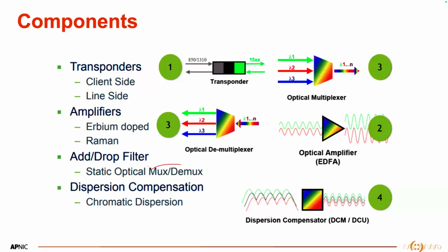It is a card which will carry all the wavelengths. Now, the multiplexer and the demultiplexer, they both are the same. The only difference is the multiplexer will multiplex the signals, the demultiplexer will demultiplex the signals, but their lambda list will be the same. The list of channels they support will be the same in one single system. It cannot be different.